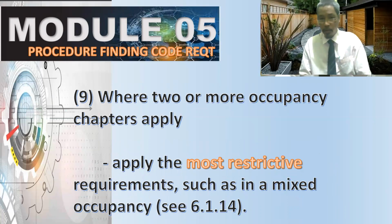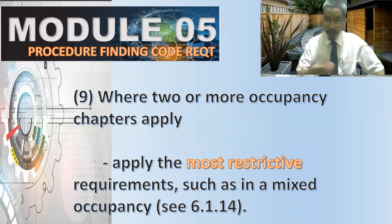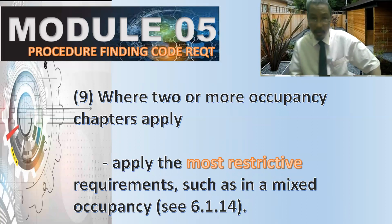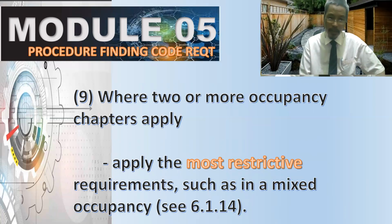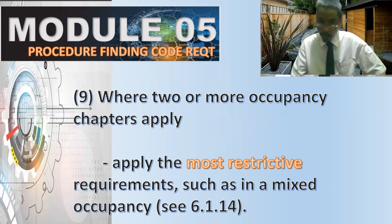And wherever 2 or more occupancy chapters apply, meaning if our area is a combination or mixed application, mixed occupancy, combination occupancy, separated occupancy, and so on, we have to apply the most restrictive requirements, such as in a mixed occupancy, paragraph 14 of section 1, chapter 6.